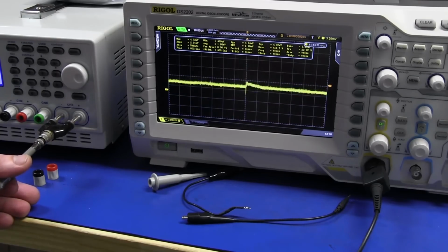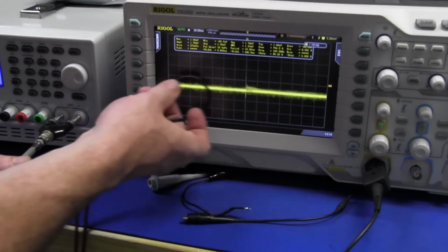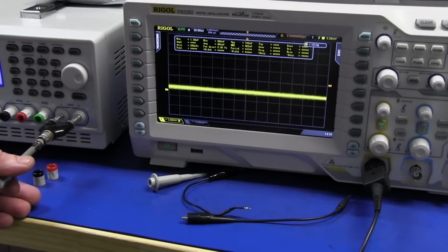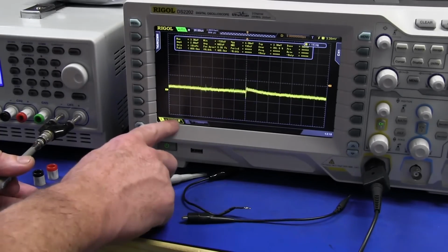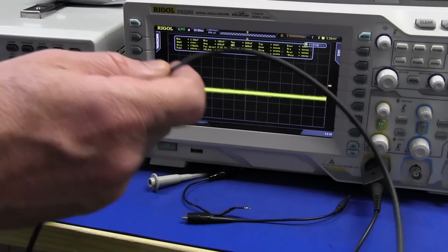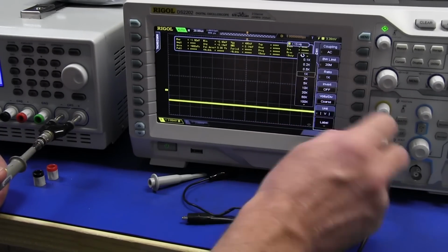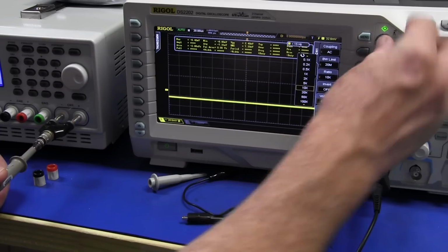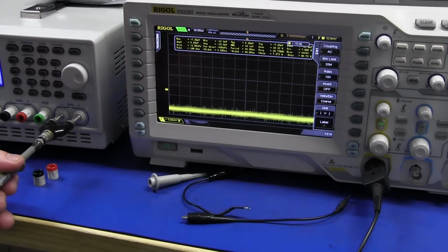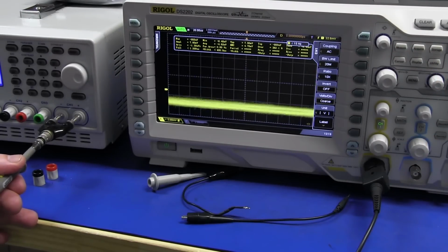Suddenly, with this good quality, properly shielded, high bandwidth oscilloscope probe, look, it's not picking up nearly as much. So our performance has gone from fairly ordinary to, still at the same 2 millivolts per division, much cleaner with the scope probe. Now let's put it on ×10, and then we have to compensate. We've got to go in here and turn that to ×10, and then we're on 20 millivolts per division. We can't actually go down to 2 millivolts per division because we have to be at 5 millivolts per division, and it's higher.